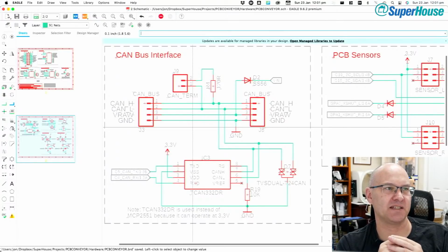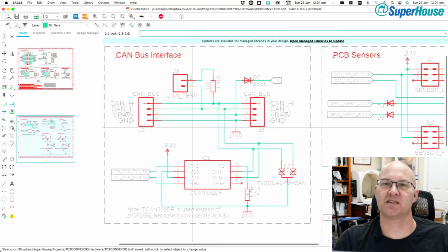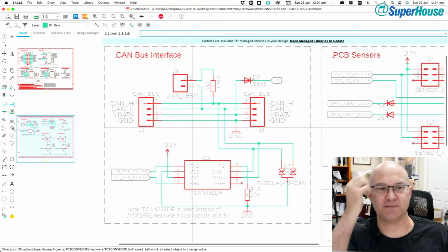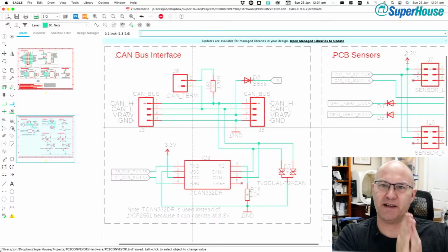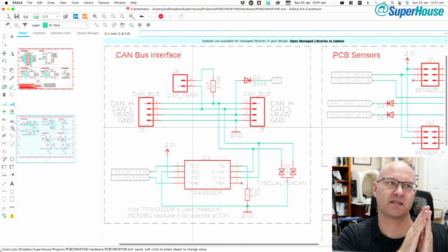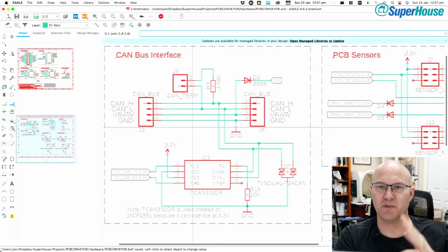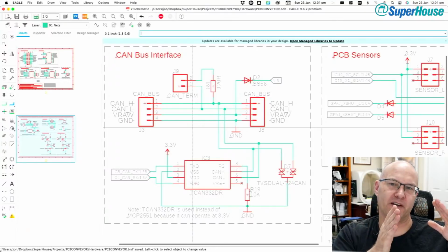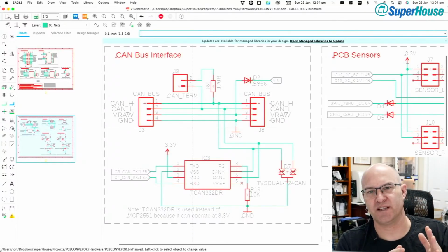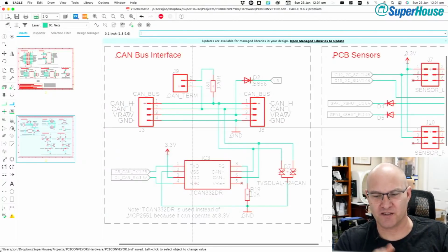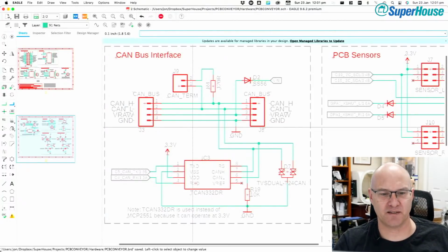Like I've seen this in UPSs, because UPSs are the classic situation where you're having to switch high power. And I saw a situation a few years ago where there was a cascade failure effect in a UPS because it had multiple MOSFETs that were switching a high power load, and you get one fail, and then all of a sudden you get extra load on the others, and then they fail, and it's like bang, bang, bang, you just blow everything.